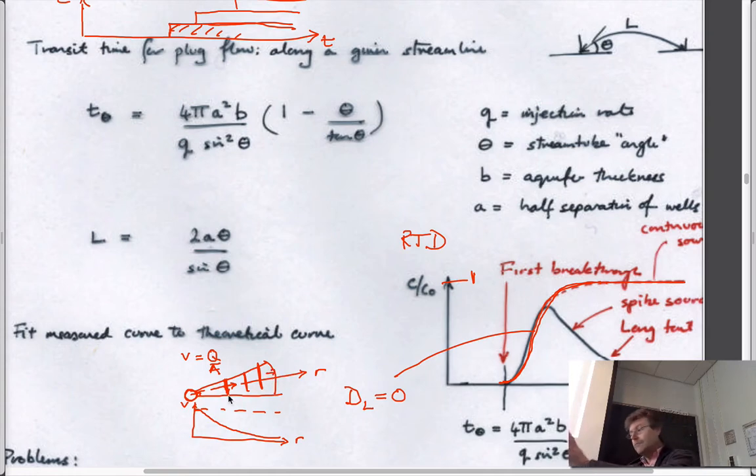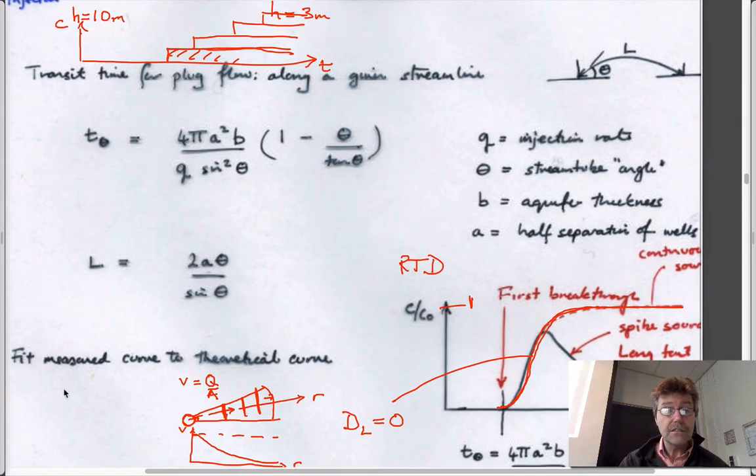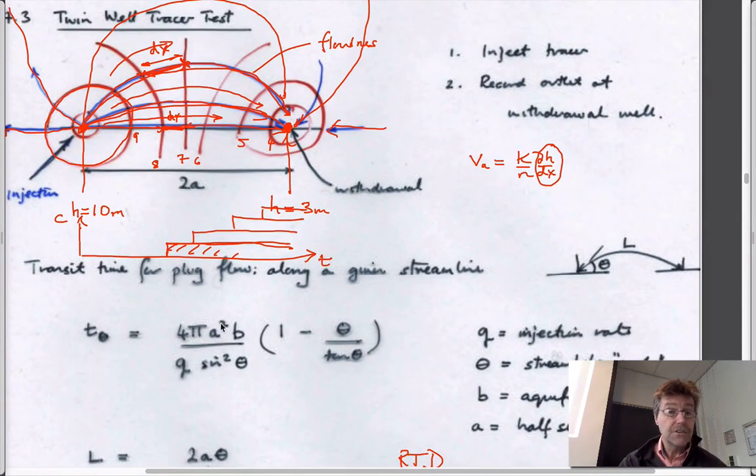So when you pump it out, it has different velocities all the way it goes out. Suck it back in, it has different velocities as it comes in, and you get mixing at different rates as a function of that. And so it jumbles up, it complicates the analysis because you can't really take account of that. It's much more apparent in this 2-well test because geometrically you could think of it as the same velocity all along this stream tube, which is fast, same velocity all the way along this stream tube, which is slower, same velocity all the way along the stream tube, which is even slower.